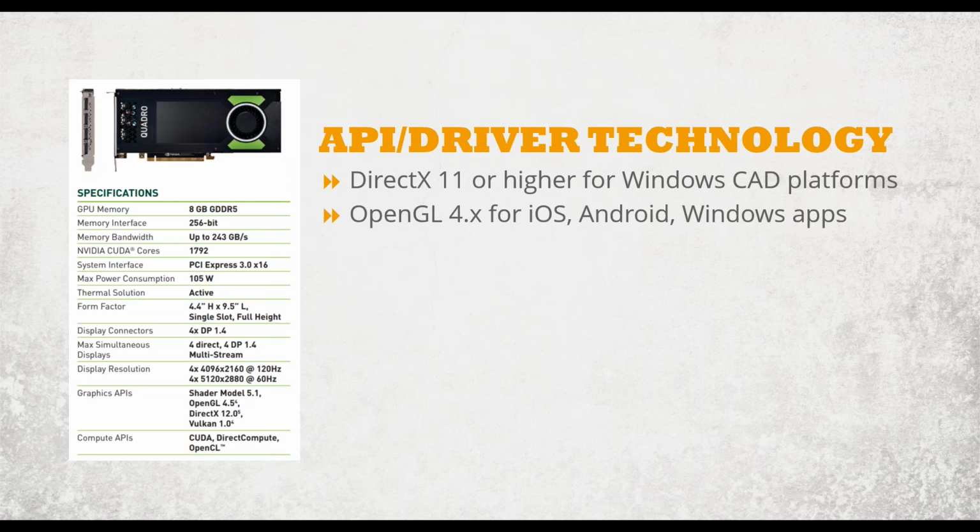For applications that can run not only on Windows but on iOS, so like a tablet or an Android device, as well as Windows apps, a more generic standard called OpenGL, or Open Graphics Language, is also employed quite a lot. So it's potentially possible that your CAD application may use both of them. So these are kind of the 2 graphics standards and driver standards that you want to be sure are present on anything that you're buying for a CAD workstation.